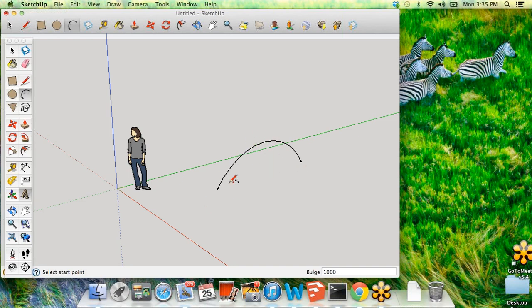When we're doing any measurements, I want to just specify this, guys. You start with that rectangle by clicking once, and then you're just moving your mouse. You can simply type in the dimensions. You're going to have the first dimension and then the second dimension, the comma in between. And that way, you don't actually have to click down here to change these. You can just simply type, press enter, and it'll fix it. All right, so back to the arcs.